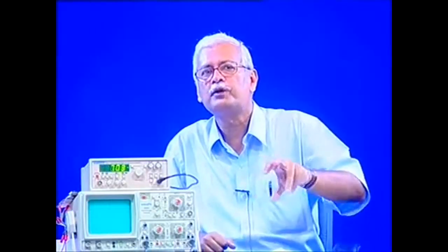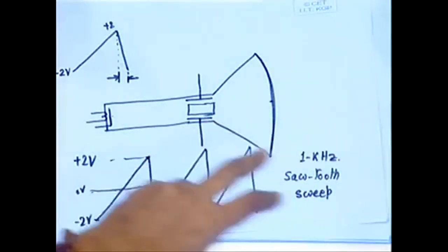Okay. So, if you are adjusting the knob of the sweep voltage, actually I will show you the controls, okay, the timing control. The timing control, actually it is done in steps, okay, that you can have 0.1 milliseconds per division, you can have 1 millisecond per division, 10 milliseconds per division, 20 milliseconds per division, like that. There is a knob which will be able to control, which I will come to soon. Okay.